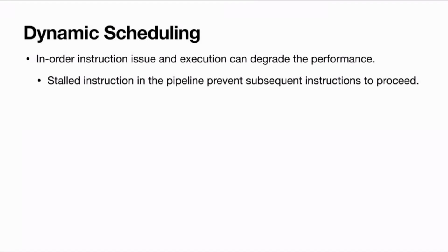If you use just a scalar pipeline, where instruction processing happens in order, that means in the same sequence given by the compiled code, the instructions are processed one at a time. We push one instruction into the pipeline processor, and in the next cycle another instruction comes in. The processor is divided into maybe 5 stages or 10 stages, and each instruction goes to the next stage every cycle.